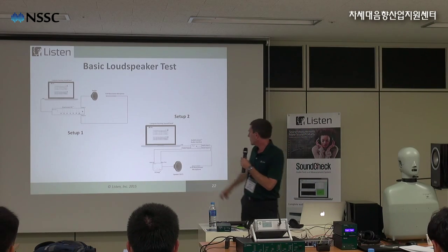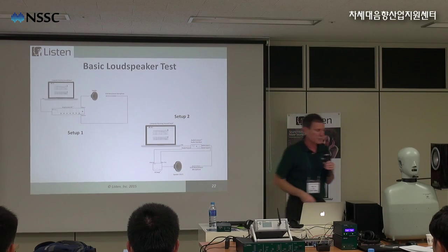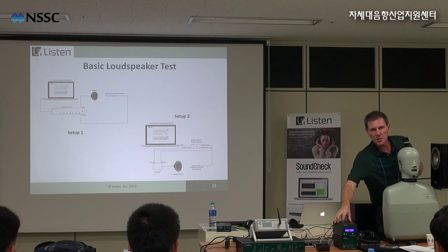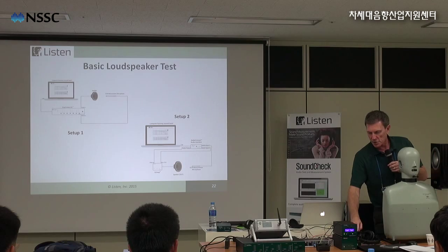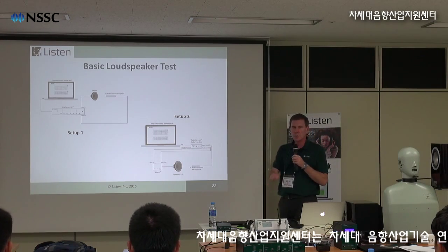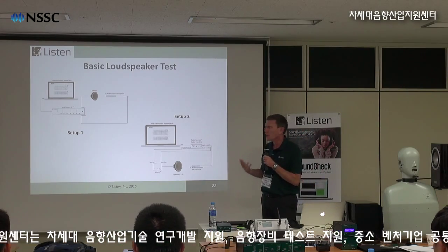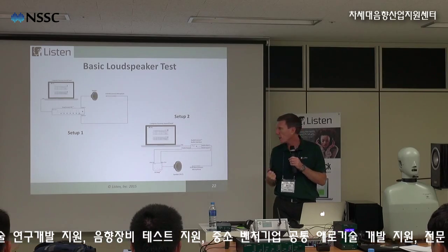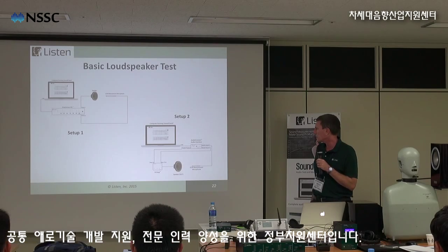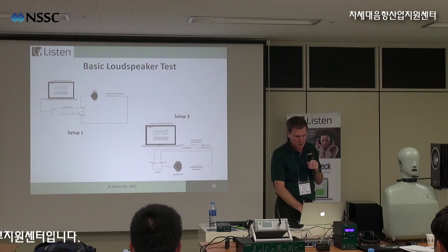That's showing this setup. Now it doesn't have an amplifier like Amp Connect. So we also have, it's hooked up here, when I was powering this loudspeaker, one of these boxes is called SCAMP, and it's just a power amplifier that can also measure impedance. Both the big box and the small one can measure impedance with an internal reference resistor, which is actually patent pending because it's built into the feedback loop of the amplifier. So these are just your typical loudspeaker setups.